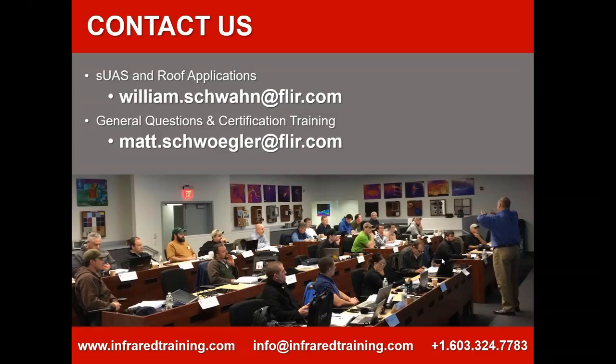Let's see. Last question we'll take from Scott asks, ever a good time to use IR on metal roofs? What's your perspective on that? Infrared on metal roofs, I have not had any success with this, Scott. And the reason behind that is that the metal is quite reflective. So if there's moisture underneath the metal, it's not going to emit through the metal like a membrane. So performing it on metal roofs, I've not had success with that, Scott.